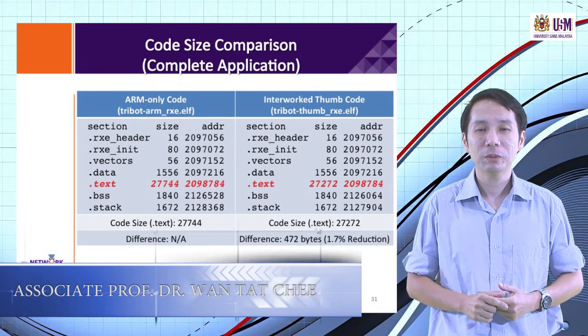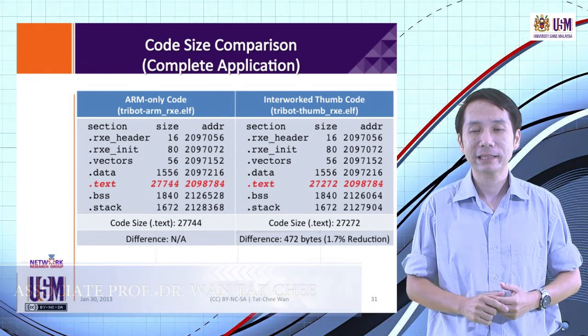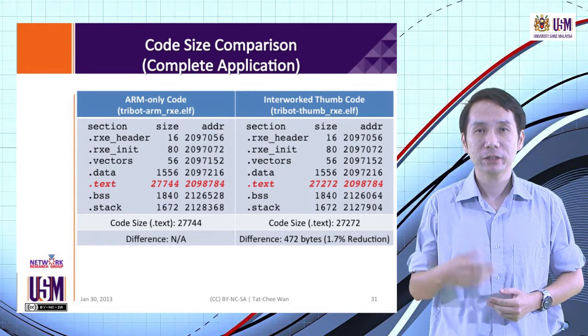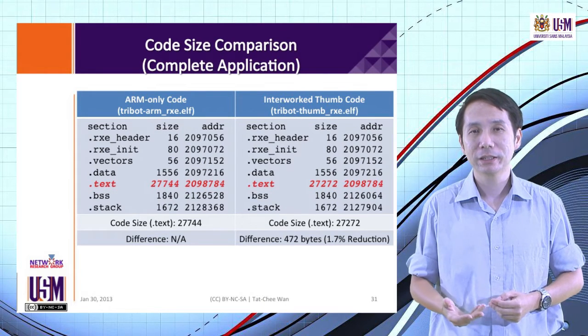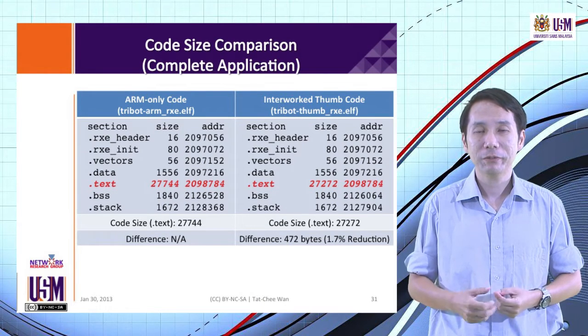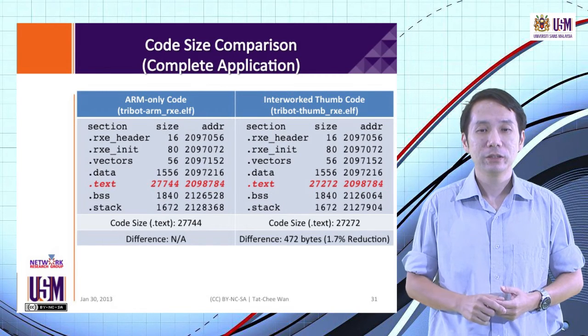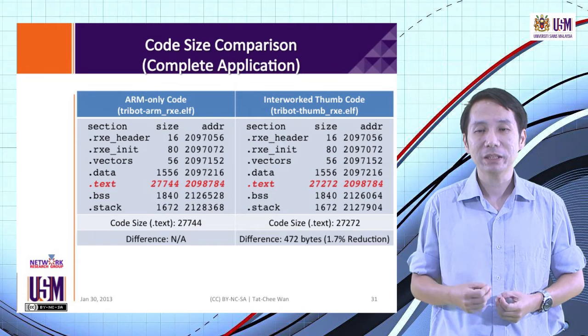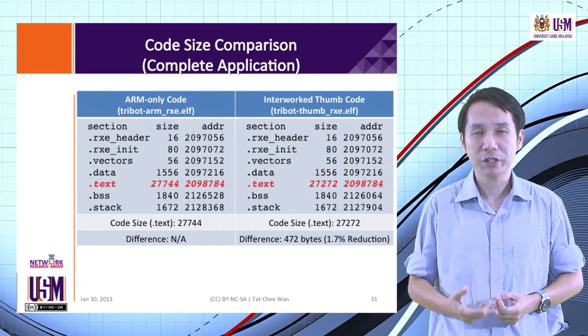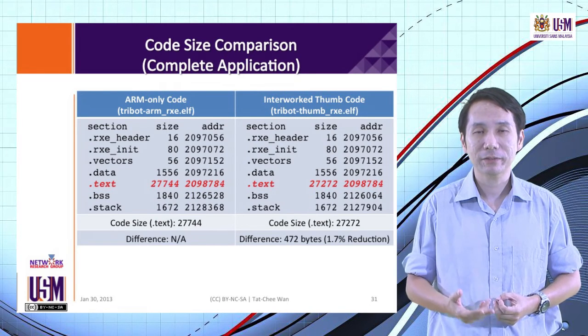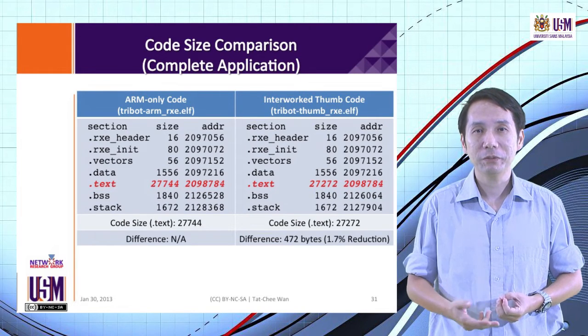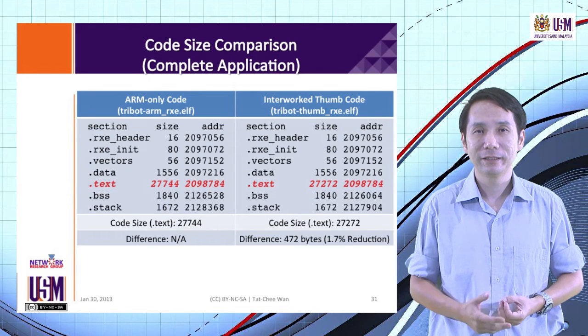Secondly, all normal ARM instructions must have the S suffix added. This is because in Thumb mode or Thumb state, all the instructions will affect the status flags by default. So this may impact ARM code sequences with complex logic which involve the setting of the status flags but modification of other register values before we actually make use of the original status flags that have been set.